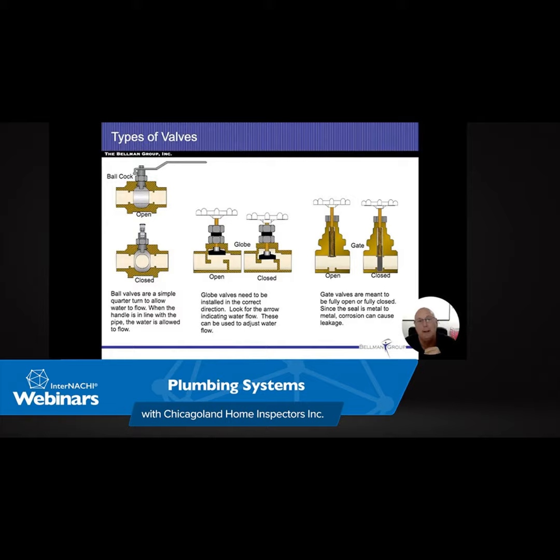What's the term that they used for that? Atomizing. So it's going to take the oil and put it through a fine mist spray, and it's called atomizing the oil because it's pretty much just a surface area that's going to ignite. So it needs to have a spray of oil as opposed to a stream of oil coming in there, and that just burns cleaner and nicer. So we have to pressurize the oil, pressurize the air, because I need to have that oxygen mixture in there when it comes through it.